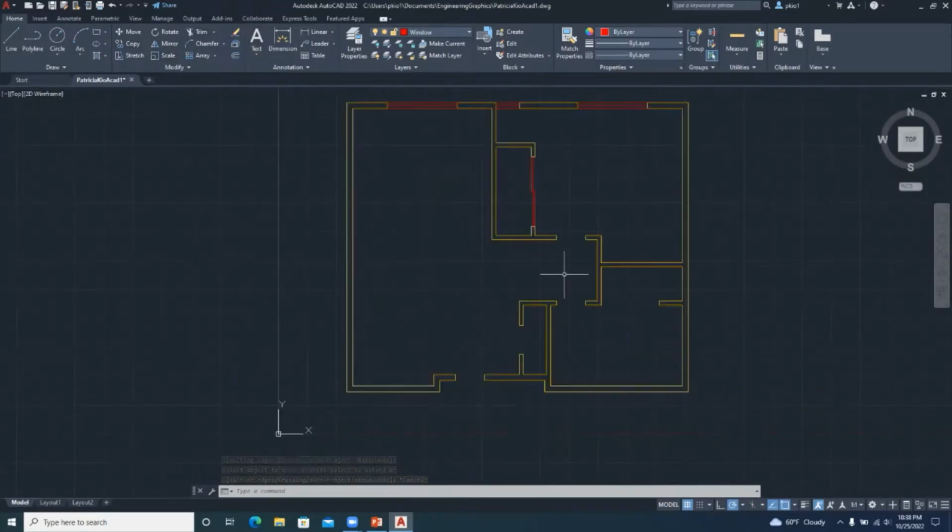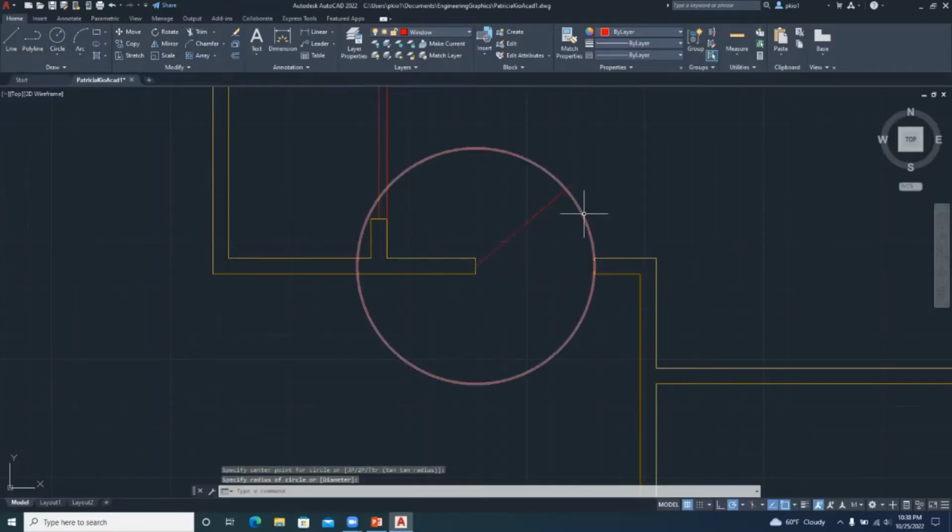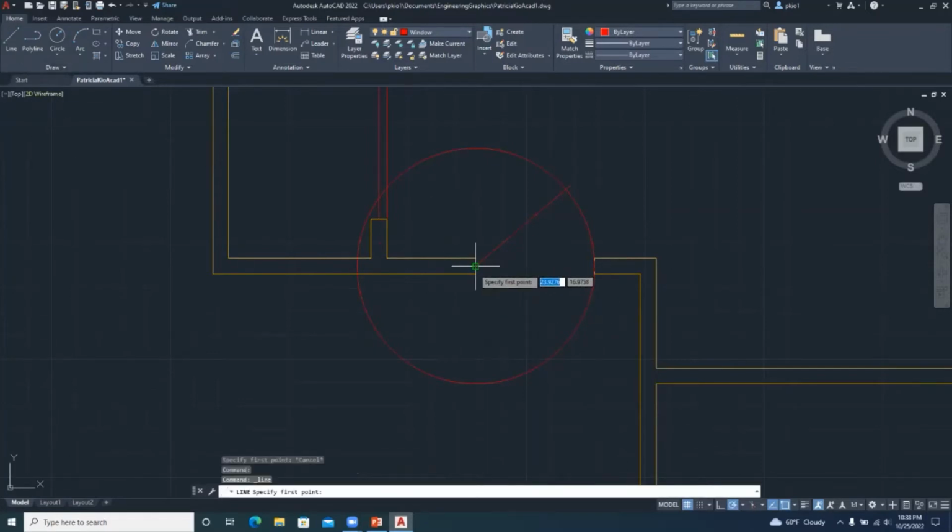And these 2 doors swing. So how we can draw the door swing, either you have objects for it or you draw the swing this way. Have 1 line, then have a circle to show the swing, and then we're going to trim that circle with a line here.